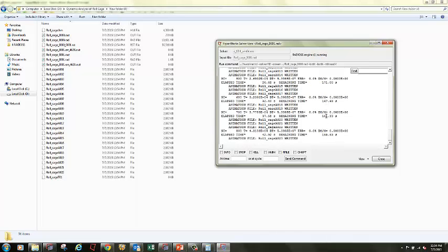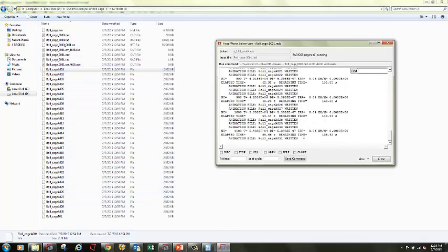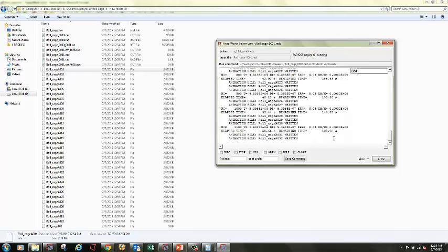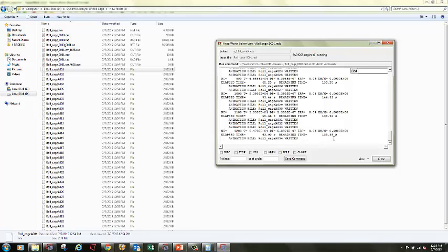because you can see each file it creates is 2.7 MB. So it will unnecessarily put load on your memory. You can increase or decrease this value as you want. It will take approximately 3 to 4 hours to solve. Once it's solved, I will tell you how to see the results and graphs.